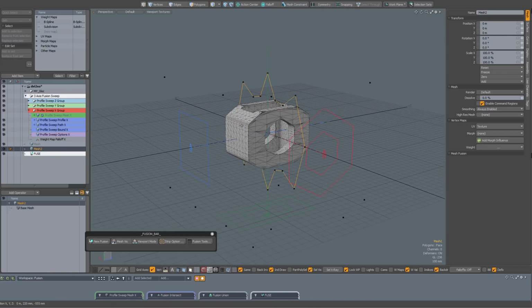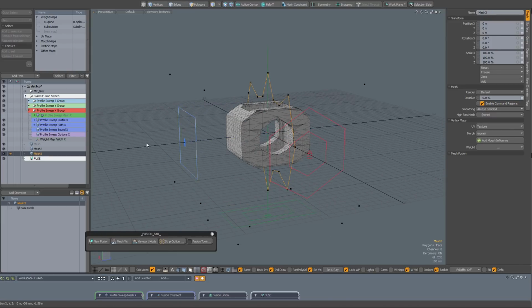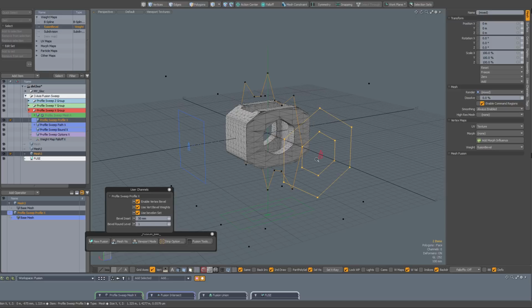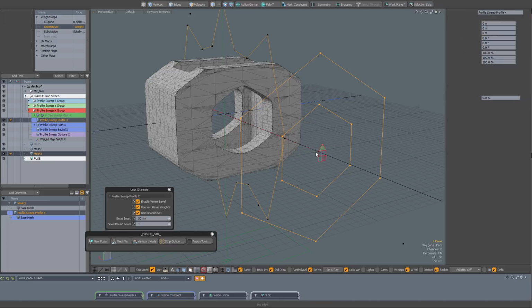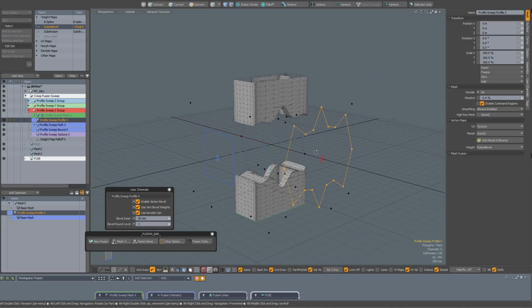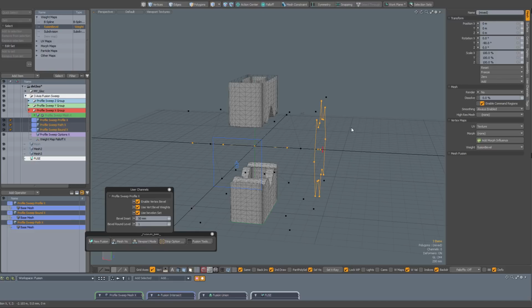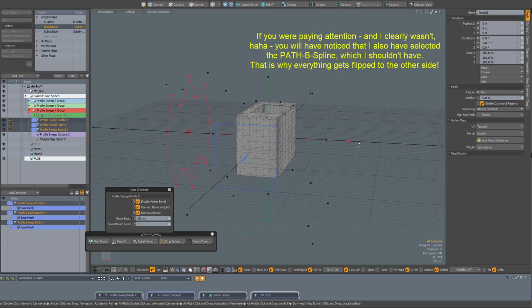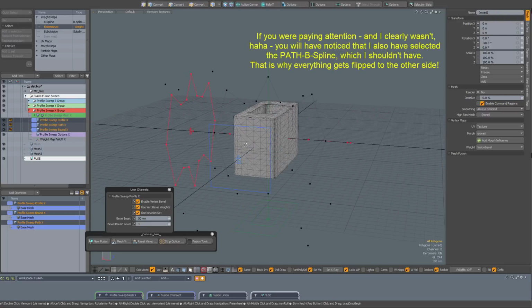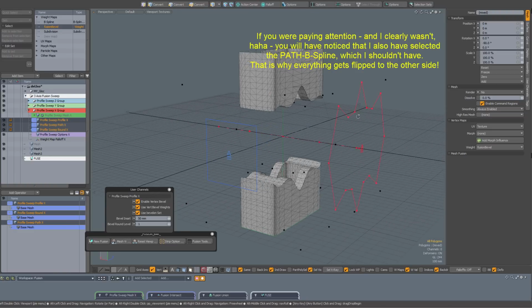Okay, drop the tool, go back to item mode, and with that item selected, I'm going to first duplicate it to have a copy. Select that item and then select also the profile, and then when you click on that triangle you can say replace profile with selection, and now that is the result. Probably my polygon has been flipped, so I'll go to polygon mode and flip it, and this happened to me earlier, that the polygon also jumps to over there. I don't know why that happens.